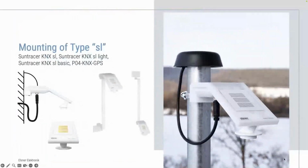In my opinion, the electronic wind measurement will always have some advantages over the mechanical wind measurement. The reason for this is, as you can see here on this picture, if the wind blows from below, so the uprising winds, we can detect them with the electronic wind measurement. This is very important for higher buildings. I would say if you have more than 4 floors, this is already a very important measurement just to assure the safety of the shading.